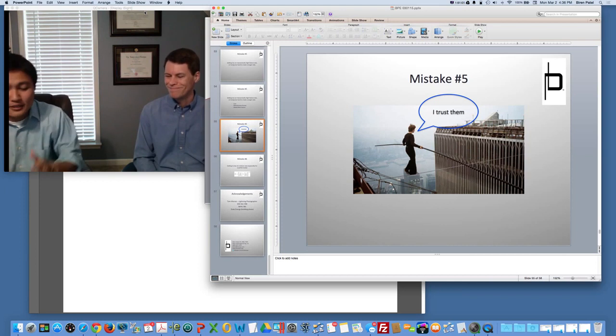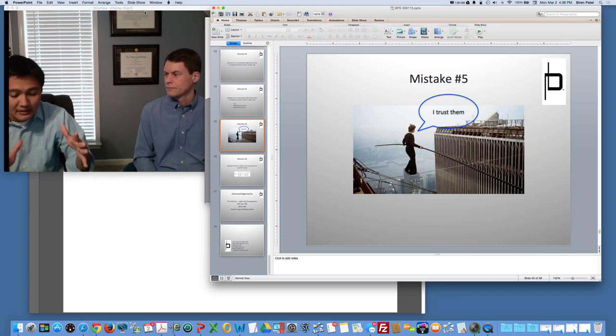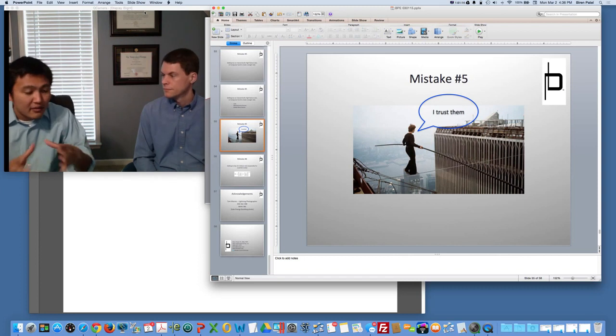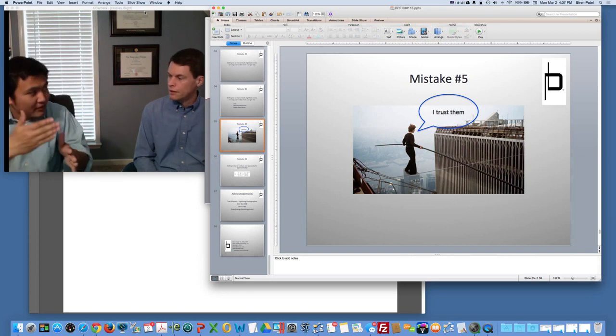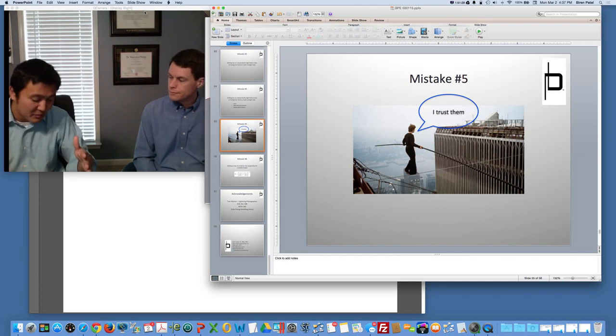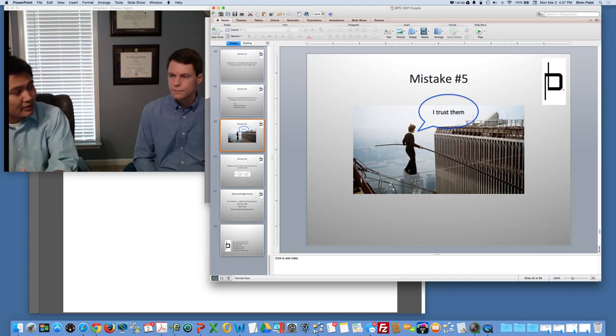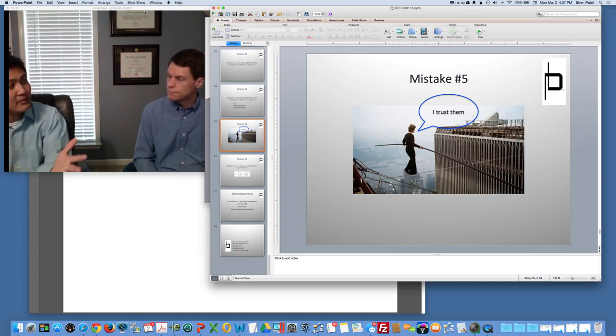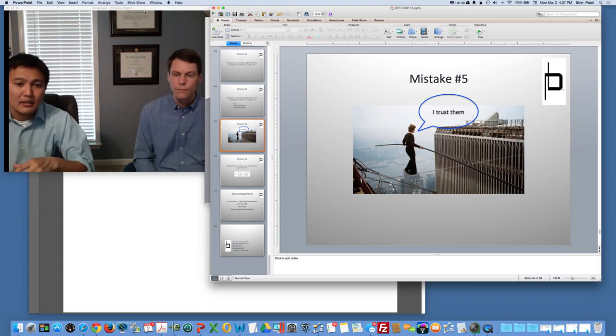Right. And I'll say this: we have a lot of clients in hurricane areas, like Florida, because obviously there's a lot of lightning in Florida, and some of our clients will say no shield wires at all. Some of our other clients will say shield wires are okay, just make sure they don't cross bus. That way, if they fall, hopefully they'll fall straight down. They won't always. There's tension and they could snap and move a little bit, but hopefully they'll fall, generally speaking, downward and not land on bus or something like that. And others say, go nuts. You put as many shield wires as you want. We don't have a problem with shield wires falling, and we care more about saving the money. So it's something to consider, something to think about with your client and the environmental factors.